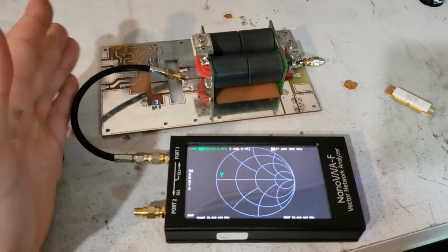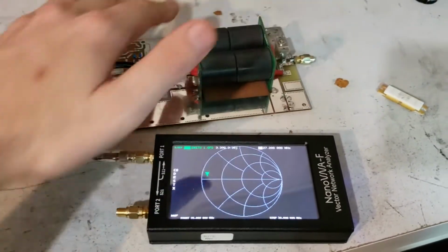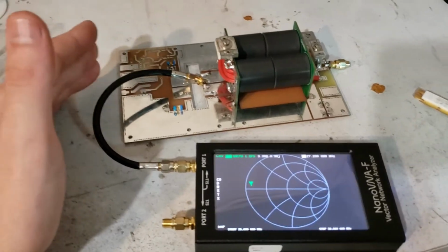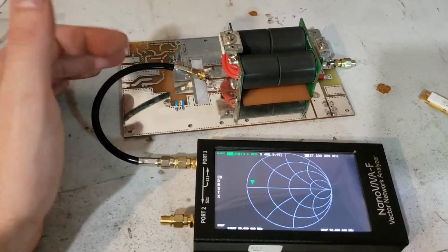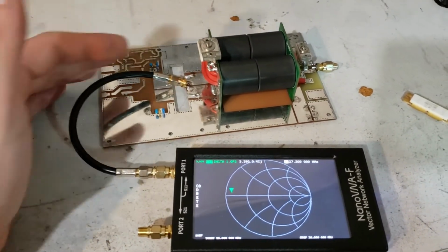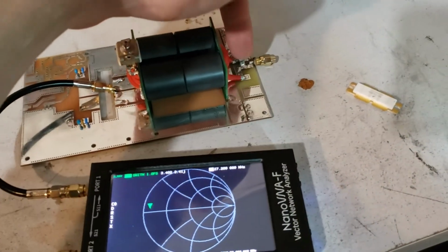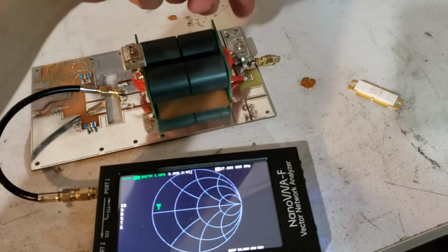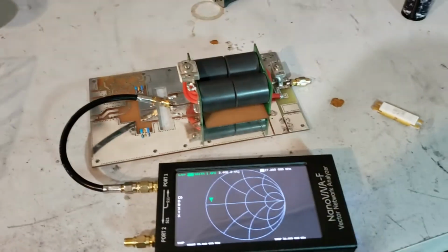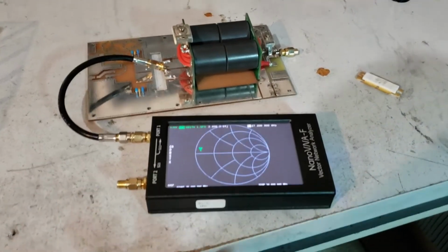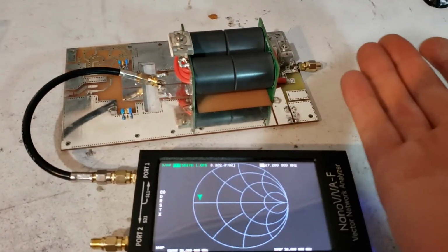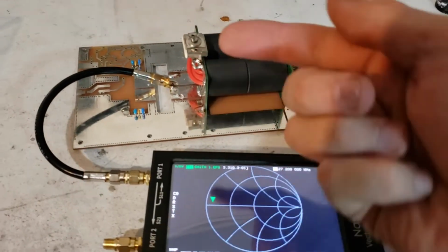Something I haven't mentioned up until this point, but this whole process works exactly the same for the input transformer. You're just doing it backwards. So the input transformer might have this capacitor across the transistors, and it might have one from the wire winding to ground. It probably will. That's how most amplifiers are going to be. And this process works exactly the same going the other direction.